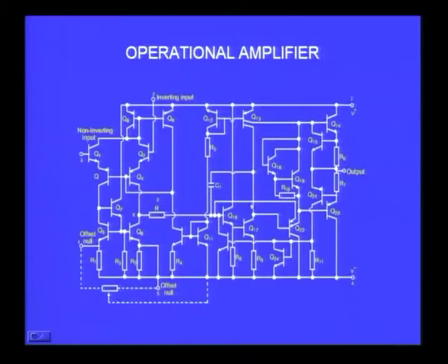Now, let me move on to show you, not to frighten you, but to indicate to you the importance of the actual circuit inside the operational amplifier. I talked to you about the operational amplifier 741. This is a typical schematic diagram, circuit diagram of the 741 operational amplifier. There are some striking things that I wish you recognize immediately on seeing the picture, and that is you find you have more transistors. The transistors are numbered here Q1, Q2, Q3, Q4 etc. The last transistor is Q20, that means you have 20 transistors in this circuit.